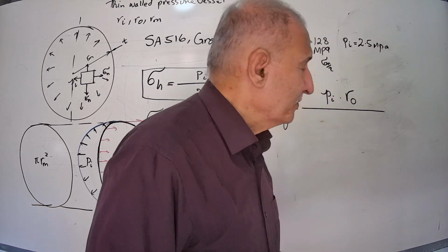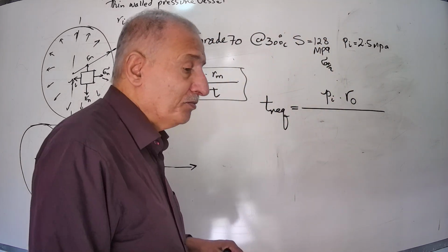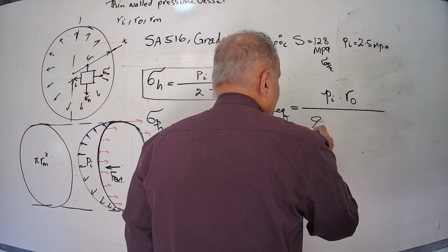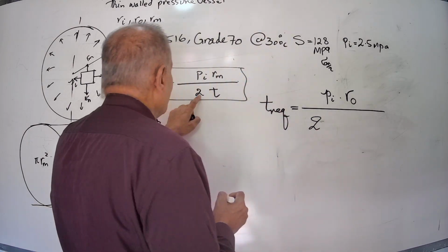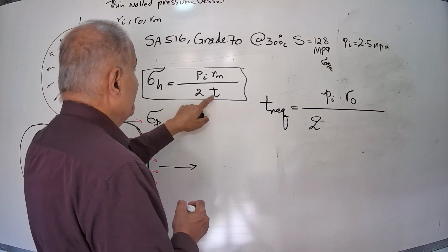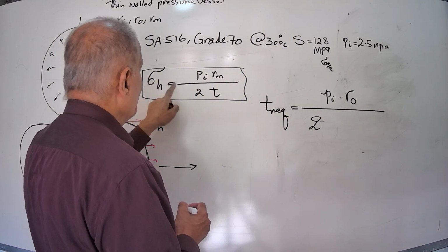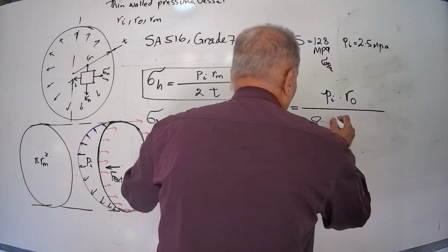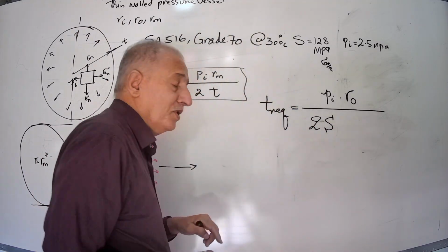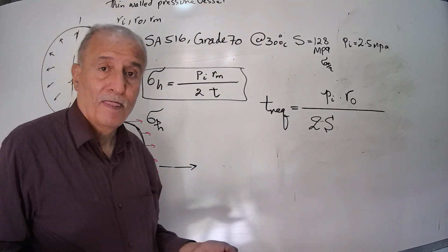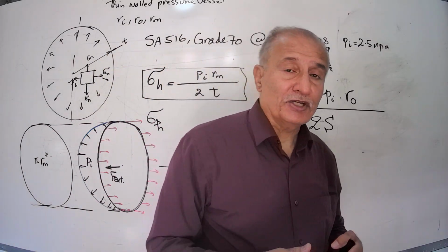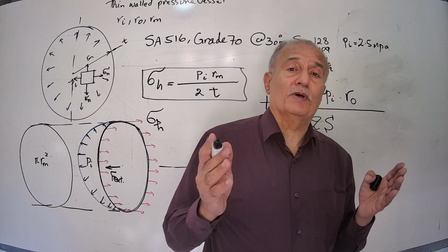It's not a considerable amount. Divide by what? Divide by 2, that is taken from here. If your thickness goes there and sigma comes here, 2 allowable stress, which is the role of the sigma. We assume that under this pressure, we reach the maximum allowable stress.